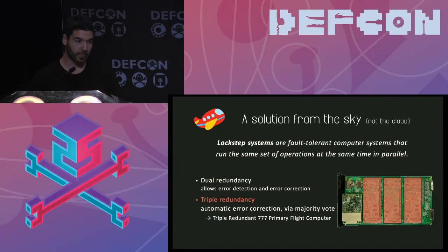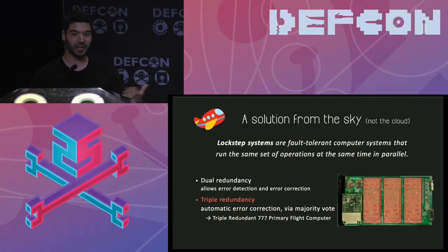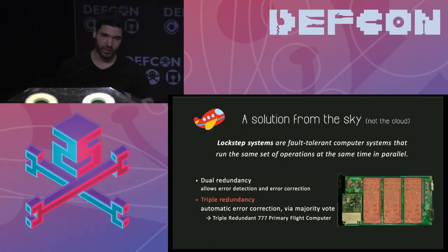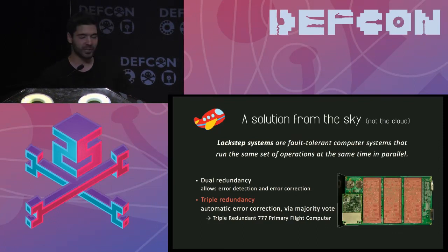Basically, instead of using one integrated circuit, they use three, coming from completely different supply chains, and they build either dual redundancy systems, which allow them to detect if one of those two circuits is misbehaving and detect errors in the final results, or triple redundancy systems where all the computations are replicated between the three different processors, and in the end they perform a majority vote about what the correct output is. This is actually used in autopilots on commercial aircraft, and I think also in space.